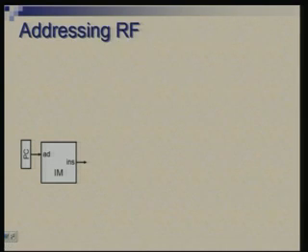Next thing is to look at the various fields in the instruction, and address the register file. Particularly for these 5 instructions we are talking of, we need to access RS and RT, which were the second and third fields in the instruction, if you remember. Bits of this 32-bit instruction which we are getting would be used to address the register file, as I discussed yesterday.